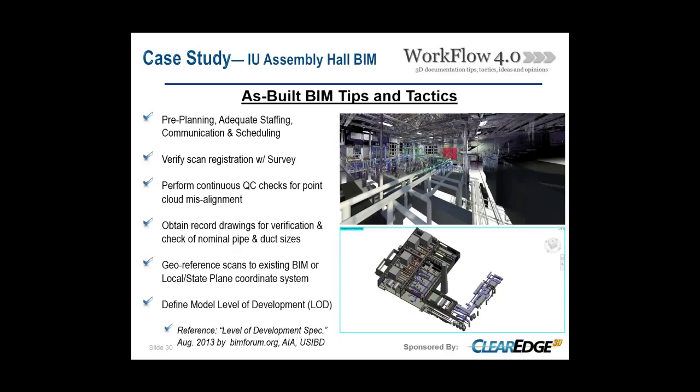Lastly, ask your client, do they want the point cloud georeferenced to state plane or even an existing model? Try to ask the questions of how you're going to be using this later on down the road. We believe that's something that you should offer to your customers.